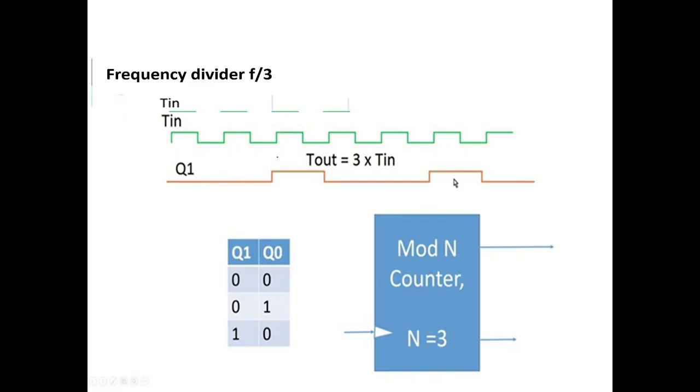So if you observe here, this is on for one cycle. This is on for one cycle. Okay. And this is off for two cycles. So this is 33.33% duty cycle. But you want how much duty cycle? 50%. 50% means what? 3 by 2. 3 by 2 means what? 1.5. It should be on for 1.5 cycles and it should be off for 1.5 cycles. So that means you need to alter the output by 0.5 cycle. You need to take out 0.5 cycle from here.